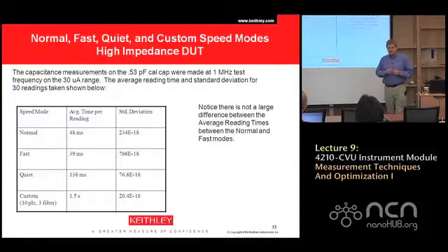Now, just a little insider tip. This particular AC impedance meter on the 4200 actually doesn't use a traditional averaging or filtering A to D converter. Basically, the way it works is we continuously digitize both the voltage and the current, and we feed those digitized signals right into a discrete Fourier transform. So we are continually transforming this signal. The longer we send this megahertz signal in, the more the noise goes down.